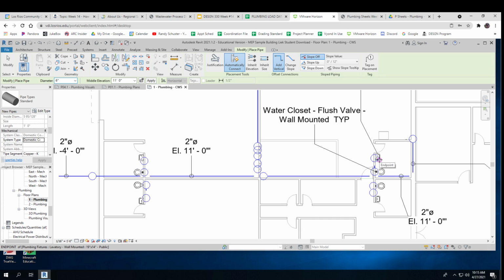Now that's got some really good stuff behind it. So hot water has to be heated to at least 125 to 135 degrees to kill Legionnaire's disease, which is one of the main causes of illness that's waterborne, that just happens. It just happens.